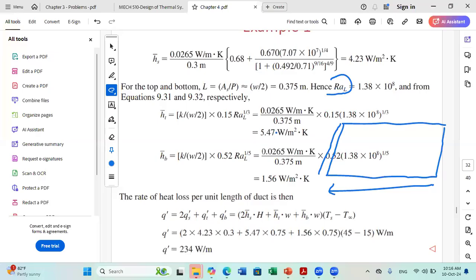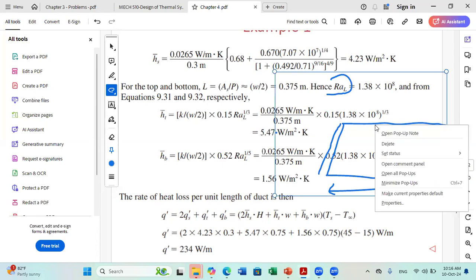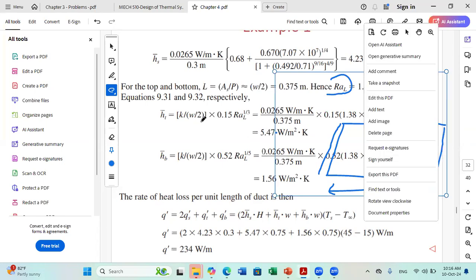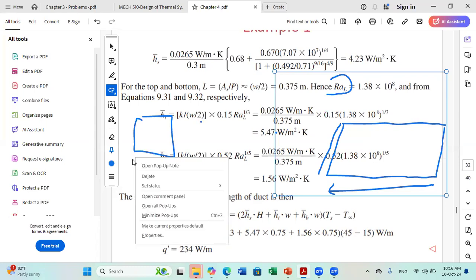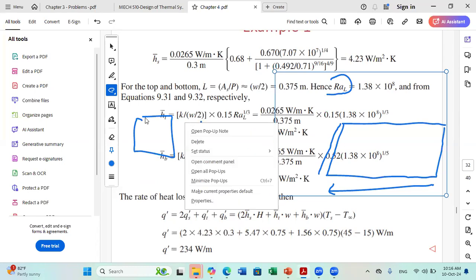Okay, so we were saying that when we want to calculate the characteristic lengths, we should consider the whole surface, okay? Not part of it. It's true that they asked per meter, but if you have a rectangle of 1 meter width and you want to do its analysis, you take the characteristic lengths for 1 meter and for W. But here you want the characteristic lengths for an infinitely long rectangular duct. So the characteristic length is based on the actual geometry.